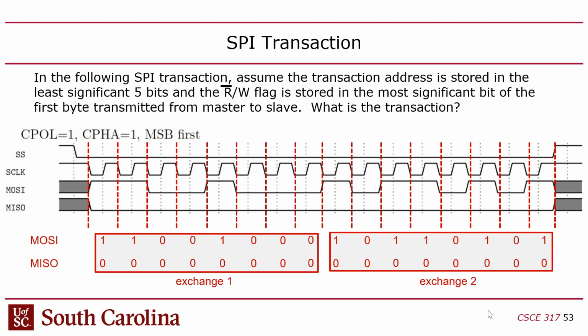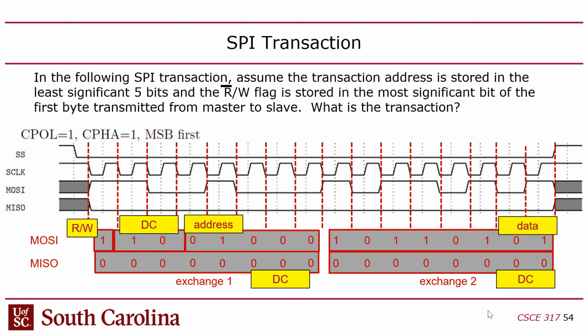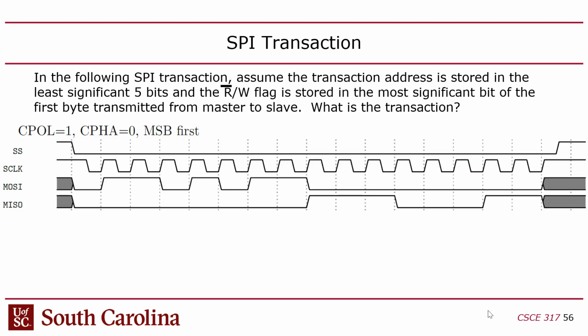Now, if there were bits in there, it depends on the hardware setup that you're using, but generally I think they just get ignored, right? Okay, and I've got everything labeled there. Read-write bit, DC stands for don't care, address, this whole 8 bits are don't cares, these whole 8 bits are don't cares, and then this is the data up here. Okay? So yeah, master writes B5 into address 8.